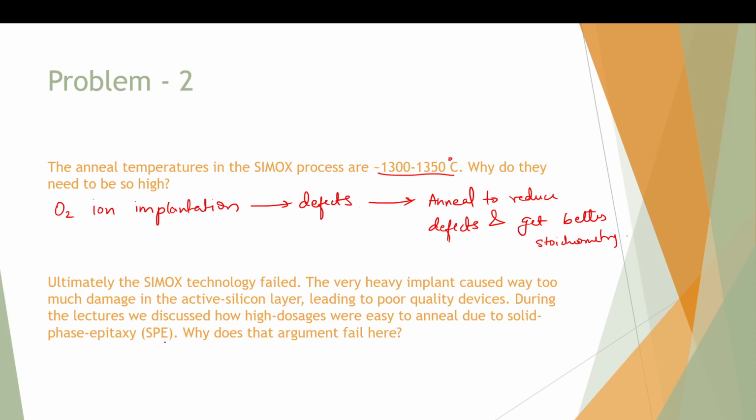That is why we get a transition from the amorphous behavior to the crystalline behavior of the deposited film. But in this case we have a silicon film on top of silicon dioxide, and then there is a substrate of silicon. The silicon dioxide, whether thermally grown or, in this case, obtained through ion implantation, is amorphous in nature.